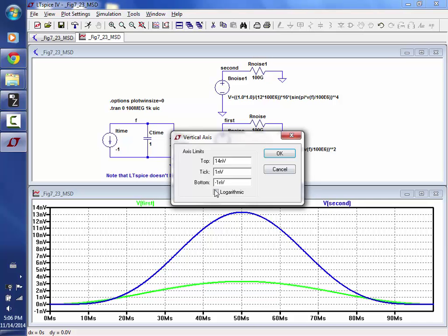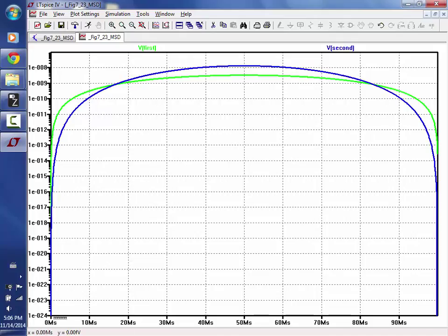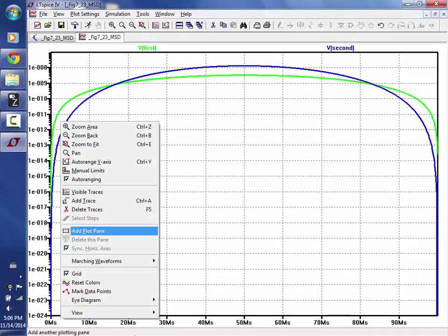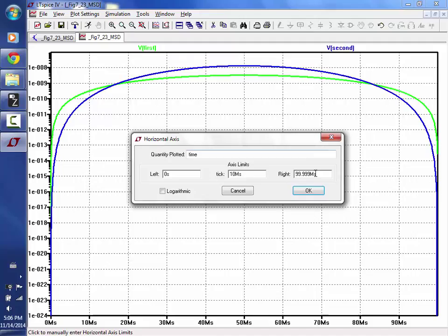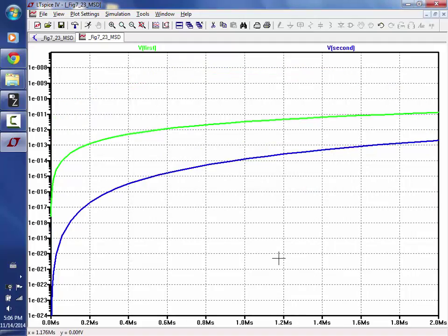Then here I'm going to put logarithmic, and limit it to, what'd you say, 2 meg? You look, and even if you go down almost to 0, the second order noise shaping is still going to be lower noise. It's only when they both get to DC that it's exactly the same, which is 0. So, does everybody follow that?